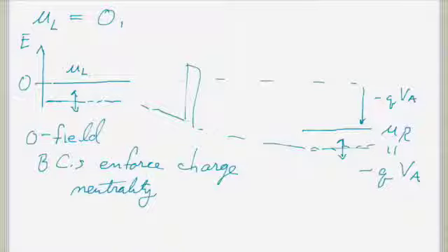And you don't get any funny stuff going on at the ends, because what they enforce really well is flat bands here at the end. So you will always get very flat bands at the end, even when you shouldn't. These always make it look really nice and flat, even when you truncated your device, made your device too short, and the fields physically shouldn't have gone away by then. You will always get zero field at the end because that's your boundary condition. So you still have to be careful. You still need to make your simulation domain large enough so physically the fields could have decayed away by the time you get to the end.